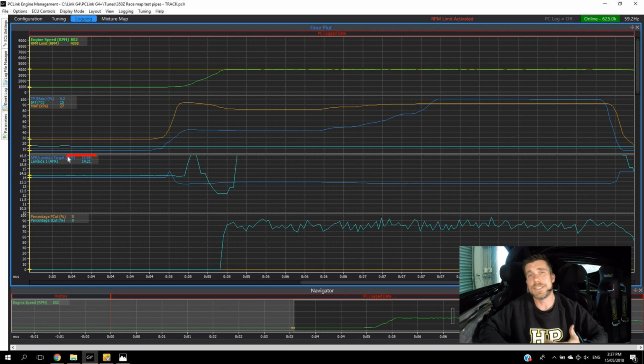and that's just worth quickly talking about. While it doesn't really have too much effect on our rev limit action, what is often overlooked is that when the engine is experiencing a cut on a rev limiter, we can't take any notice of the air fuel ratio reading from our wideband sensor. This is actually exactly the same scenario if we also have our engine suffer from a misfire. And what you're going to get is a momentary lean spike, and this is because we've got unburned fuel and oxygen going through the combustion chamber,